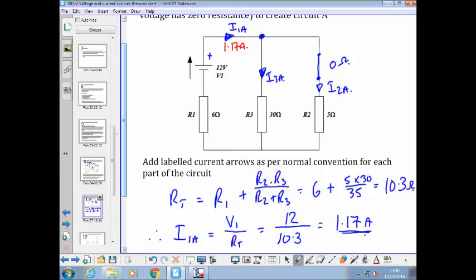Yeah, but what if we were to draw voltage arrows on this circuit? We've got current coming round here, so we've got a VR1 there, haven't we? And we've got a V2 there that's across both of them because they're in parallel. Do you agree with that, Carl? Same voltage across two parallel resistors. Electrically, that point there is the same as that point there. Agree with both of those things? Yeah?